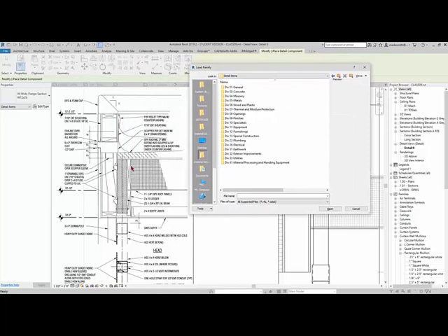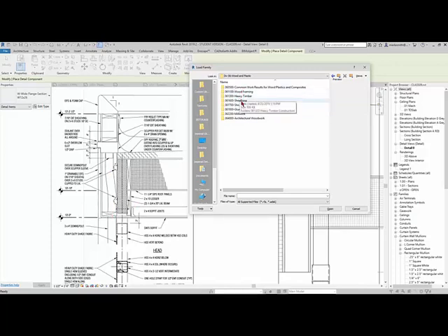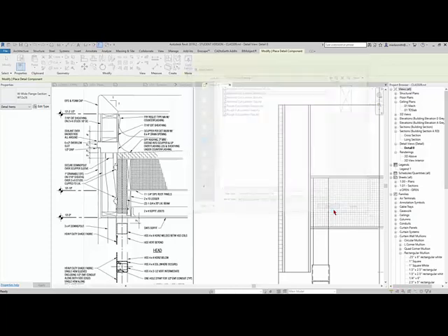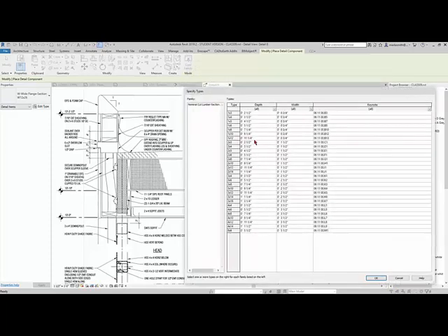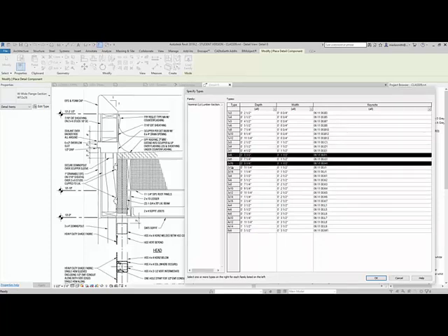We've got a lot of wood in here, so I'm going to go into Wood and Plastic, right? And I need some wood framing, so I'm going to need some 2x10 ledgers. That's a 2x12. These are 2x6s, so I'm going to get a 2x10, a 2x12, and a 2x6 section cut. So if I go to Wood Framing, there's a nominal cut lumber section. That's non-continuous, and that's continuous, right? So I'm just going to open nominal cut lumber section, and it's going to give me all the different sizes over here, and I want a 2x6, a 2x10, and a 2x12.